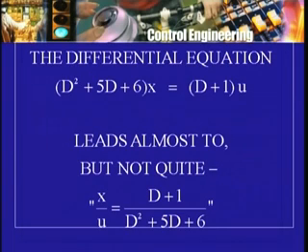Because first of all, as I told you, the transfer function is not x(t) divided by u(t) at t equal to 0 or 5 or 20 or 10 raised to 3 seconds or whatever. It is not a ratio of output or response value to input value. No, it is a ratio of Laplace transforms. So on the left hand side, x by u makes no sense. I can of course take x(t) divided by u(t), but that is not the transfer function.